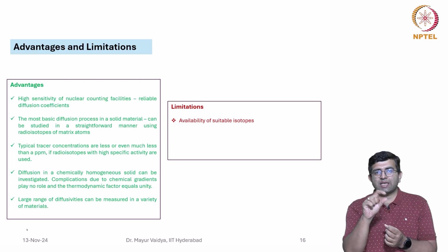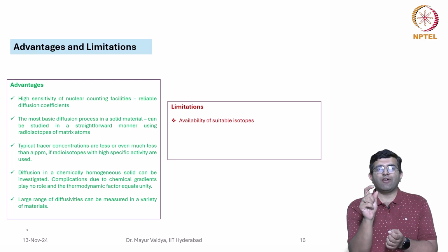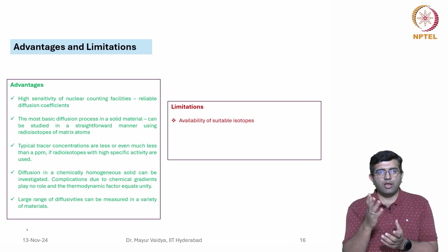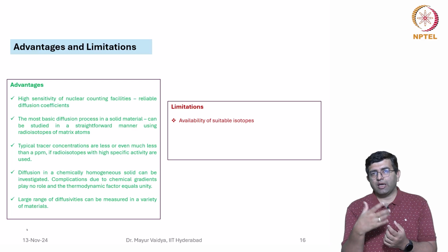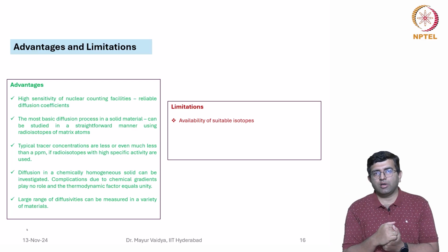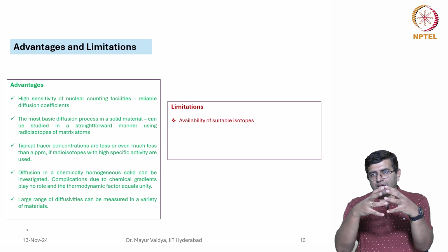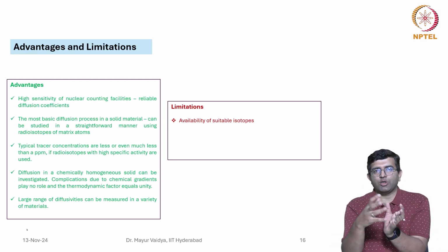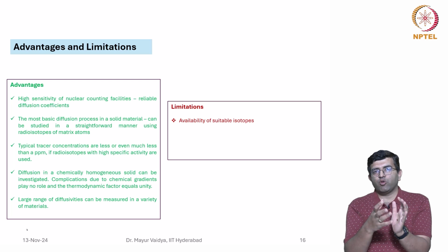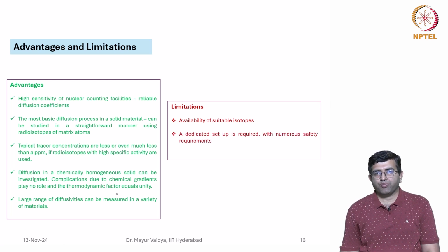For example, if you want to measure the diffusivity of scandium, people do measure it, but the scandium half-life, if I remember correctly, is a few hours. Zirconium also, for example, has very short-lived isotopes. So then you have to complete everything within a specified duration, and you have to take care of the half-life corrections and so on if you want to measure any reliable diffusivities.